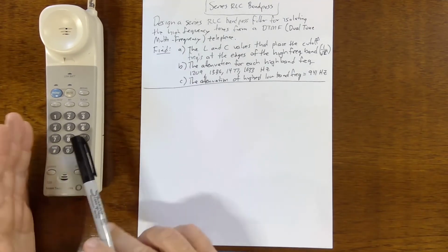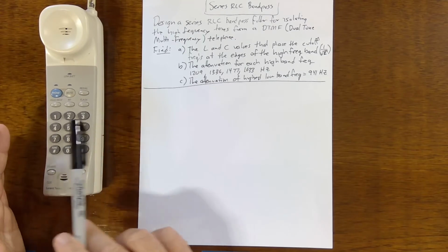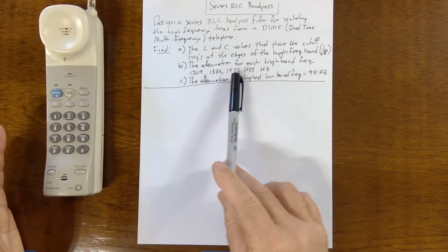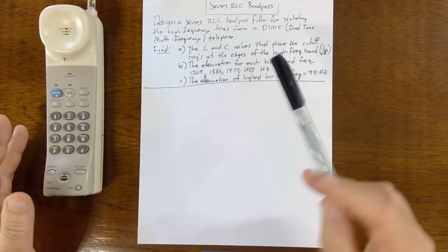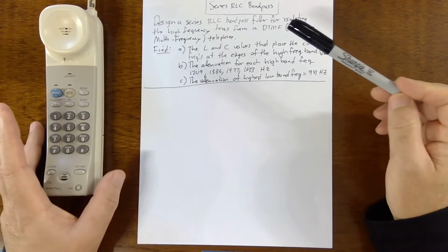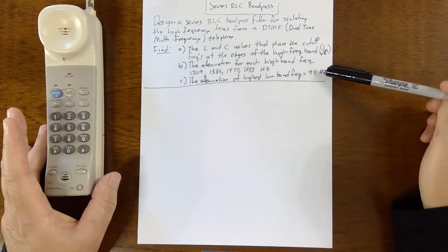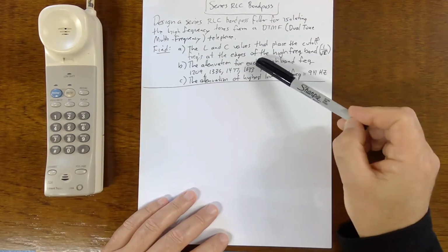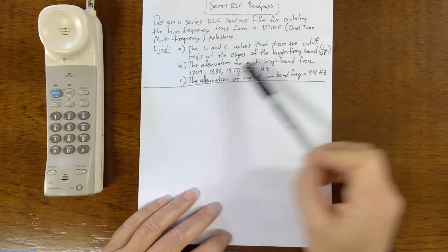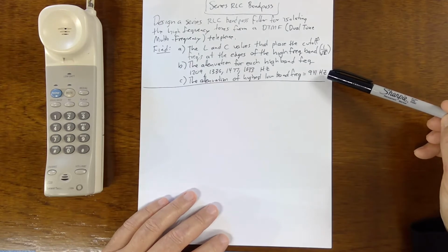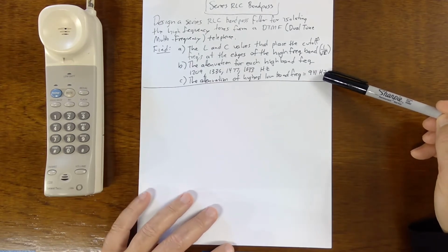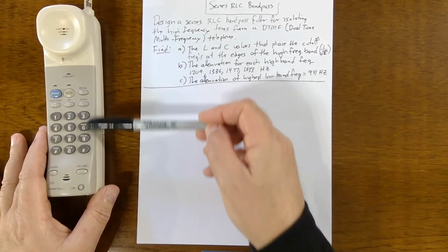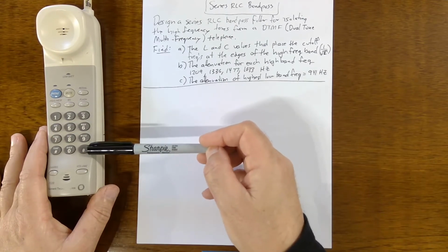And then there's 4 frequencies on the rows, and the highest column has 941 hertz. So our problem is we just want to filter out the high frequency band just to let that go through so that we can analyze that further. So we want to send just one of these 4 high band frequencies through, okay, and filter out everything else. And then we, as a measure of how well this high band pass filter is working, we want to analyze the attenuation of the highest low band. So the low bands are on the rows, and the highest low band is 941.